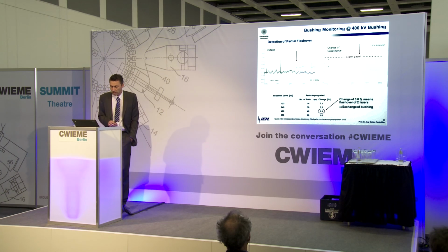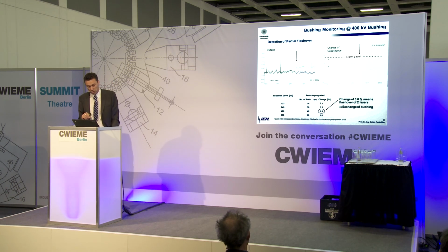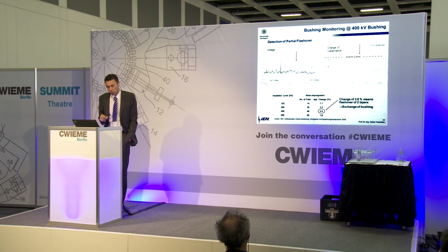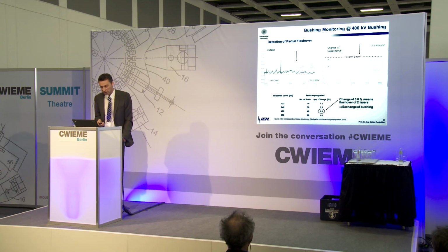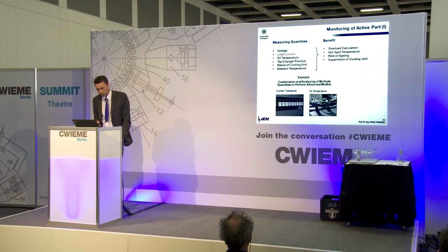This bushing was then exchanged and investigated, and indeed the flashover inside the bushing was found. For sure, if this bushing had been kept longer in operation, this problem would have developed into a full flashover of the bushing, with explosion and fire and all these bad results of a major failure.